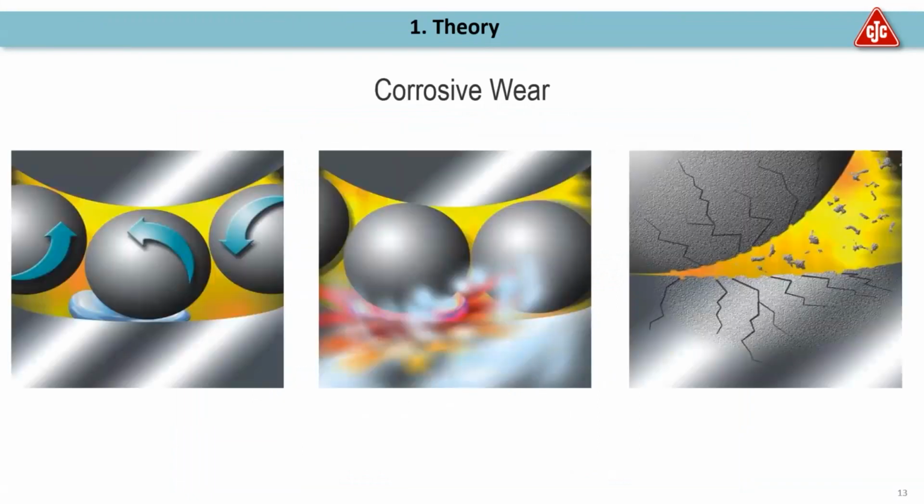Corrosive wear: water is just as hazardous to a lubrication film or machine components as hard particles, especially in gears and in bearings. When small water droplets get between two high pressure zones, like here, a ball in the bearing shell, they explode under high pressure, causing hydrogen embrittlement, and also, of course, no lubrication film at all at that point, causing damage to your machine components.